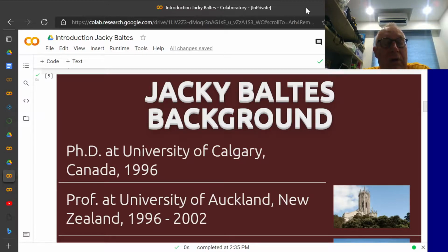But if you have 20 choices, then you're looking at 1 million, 2 to the 20. If you have 30 choices, then you're already looking at 1 billion. So if you have 100 choices, it will take thousands of years before a robot can figure out a plan to make a cup of tea. And this, what's called combinatorial explosion, this exponential complexity of the problem, makes it intractable for anything but very small problems.